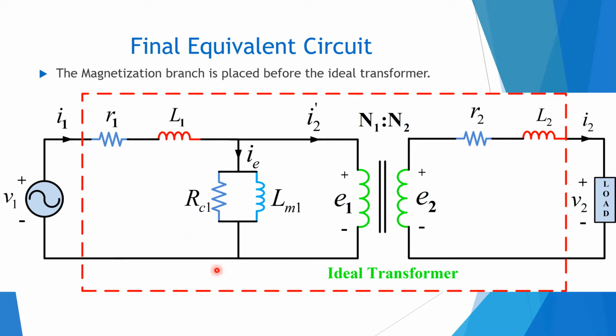Now this is the most important diagram in transformers. This is the equivalent circuit. So let me explain what I was talking about, the referred currents, right? I have some current I1, and since this is an ideal transformer, the current through this is I2 getting referred, that is shown by this symbol at the top, I2 prime. Now I2 prime is N2 over N1 times I2, and the difference between these two currents is what is flowing through here. So if in this branch I have I1 minus N2 over N1 times I2, I could simply put the magnetization branch here and be done with it.